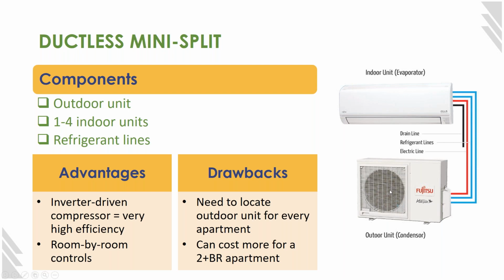And for a studio and a 1-bedroom and a 2-bedroom, they've gone with a ductless mini split, just like this, with one of these indoor units in every bedroom and the living room. And then once they get to 3, 4, 5-bedroom, they've actually found that it was cheaper to go with a ducted system, like a ducted mini split. So instead of one indoor unit in every room, they'll go to a ducted fan coil, still powered by this inverter-driven compressor outside.